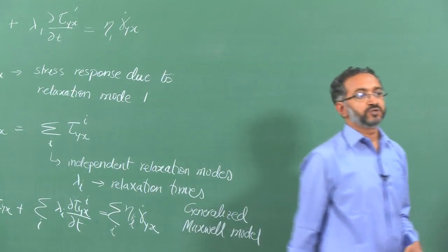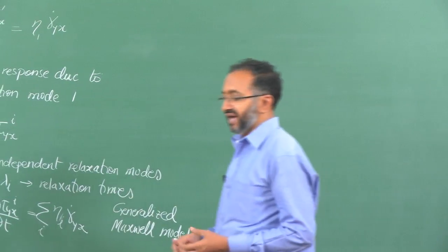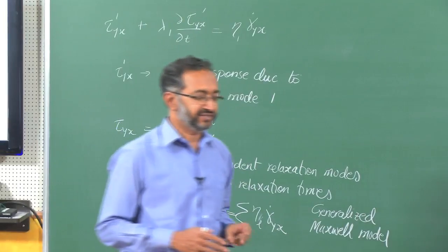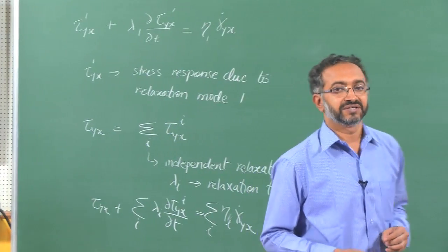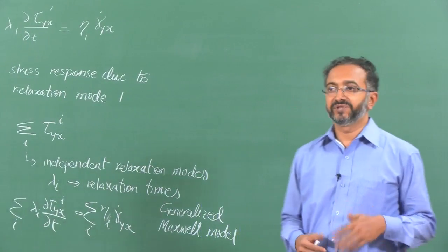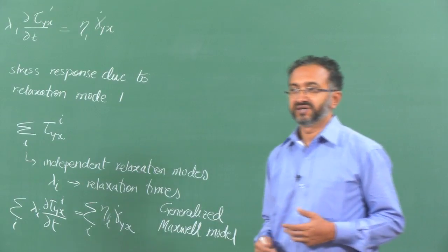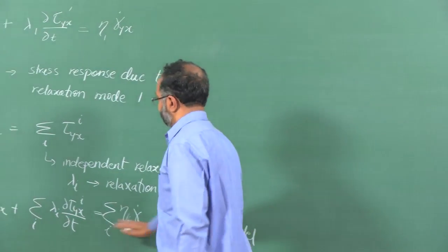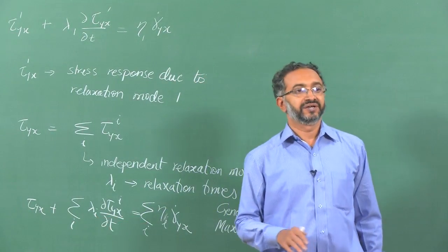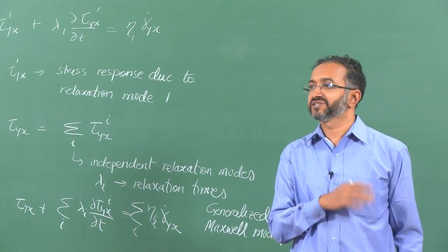And so, this would be useful for fluid like materials, as we will see towards the end of this and the next class, that for solid like materials we will need an additional set of terms to describe the non-terminal viscous response. The fact that no matter what is the set of relaxation times we use, in this case at very low frequencies we will always get terminal viscous response.